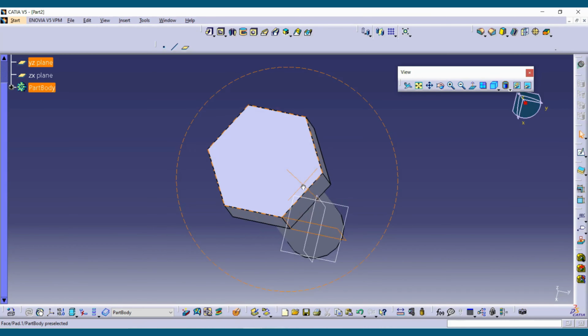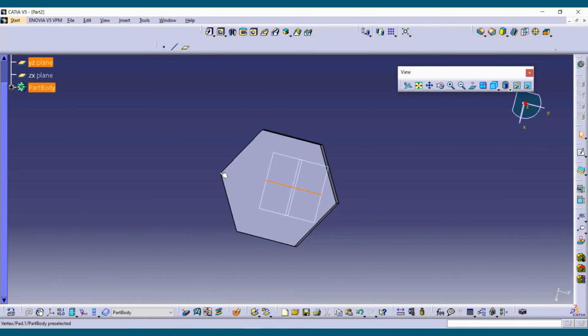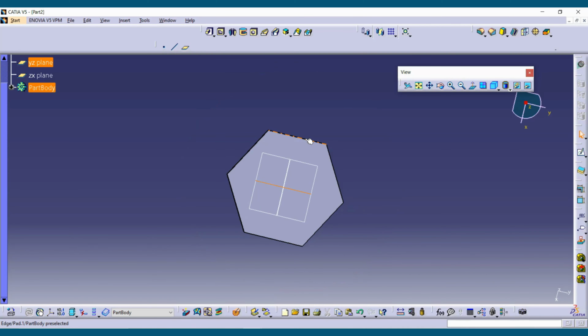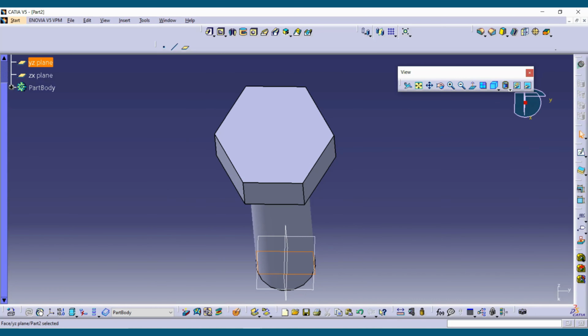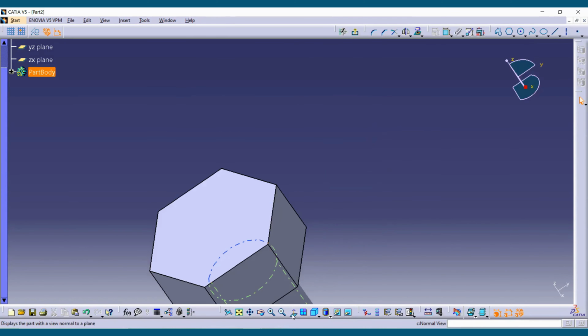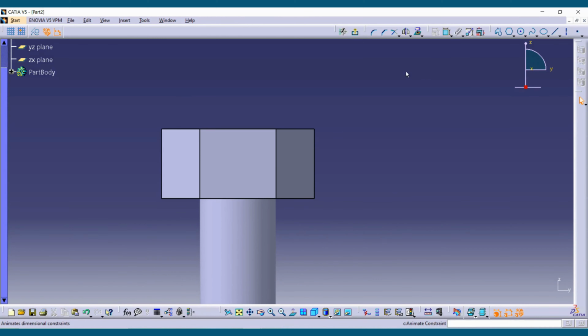So this will be the plane. We can see it is passing through the corners here. No other planes or faces will be valid for the groove cut other than this maximum distance crossing plane. I am going to say sketch, and we are going to make the profile. Make it normal view. Before that I am going to select both these edges and say project 3D elements. So these edges will be projected as sketch elements for reference purposes. Make them construction elements.